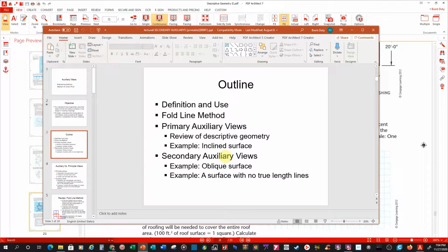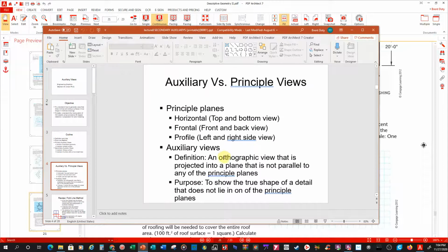Well, that's whenever you can't just flip it once. It's one of those deals where you have to flip it twice or 3 times to figure it out. So the other thing when we're talking about this is what are your principal planes that you're dealing with? Well, if you think about it in SolidWorks and Inventor, you have 3 basic planes that you start off with. Those are also called datums because they're references. They're reference planes or reference surfaces. Well, a plane is a surface. It just has a direction basically.